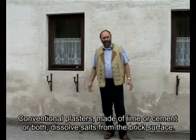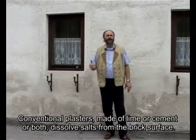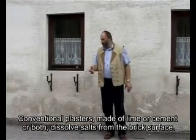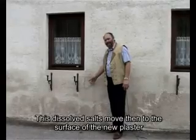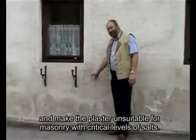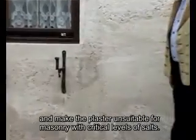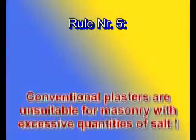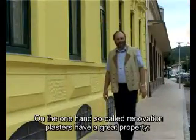Now, let's talk about plaster. Conventional plasters made of lime or cement, or both, dissolve salts from the brick surface, and they move then to the surface of the new plaster. This makes them unsuitable for masonry with critical levels of salts. Rule 5. Conventional plasters are unsuitable for masonry with excessive quantities of salt.